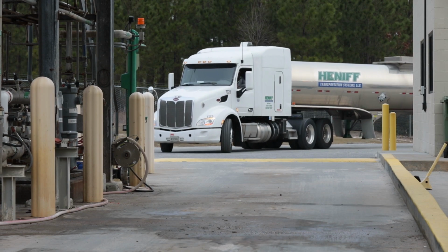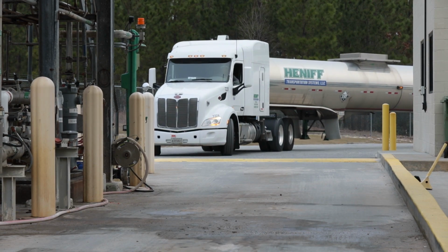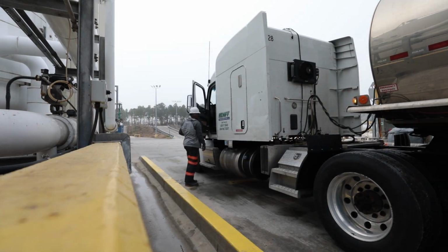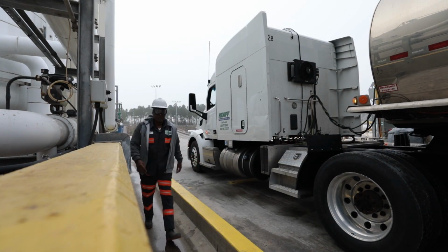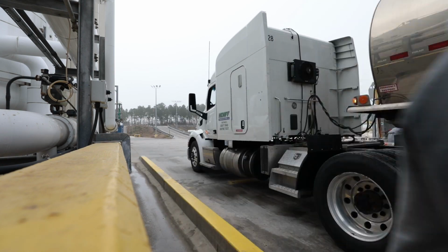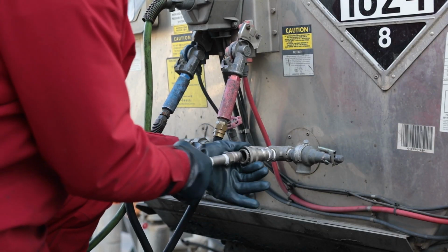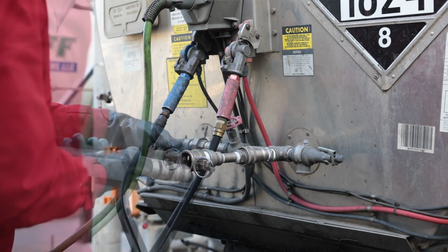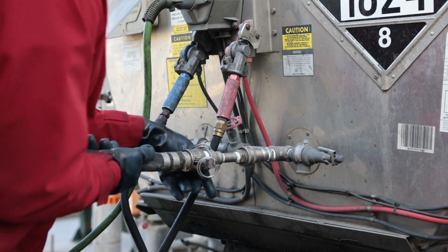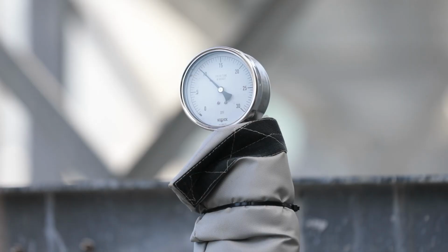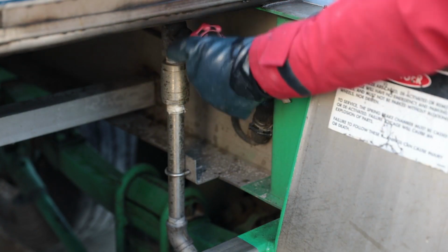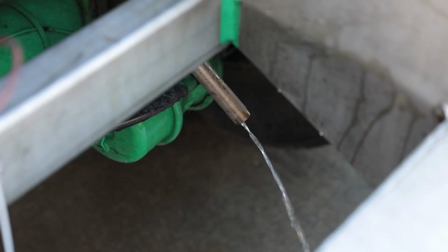Caustic may be shipped in an insulated tank truck and usually arrives ready to unload. Delays in shipments or very cold weather may require the caustic to be steam heated before unloading. Heating the tank truck with low-pressure steam through the external coils will thaw frozen caustic sufficiently to allow the caustic to be unloaded. The steam source at the unloading station should be regulated down to a supply pressure of 15 psig to prevent hot steam from damaging the cargo tank and/or its lining.